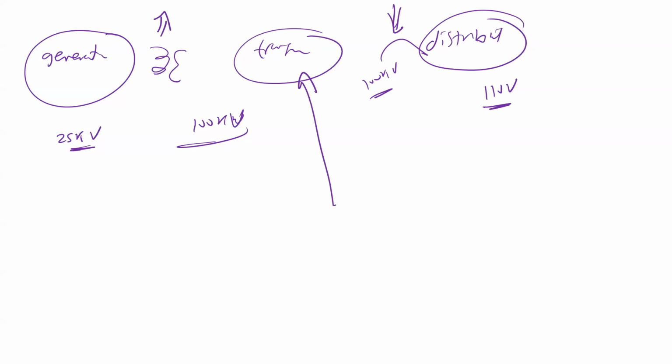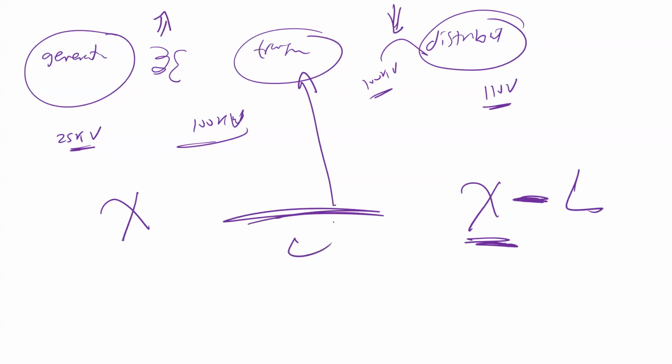But just keep in mind, if I generate an amount of power or energy X here, it doesn't mean I'm getting X here. It's going to be X minus some losses. So you lose some power. Losses are not a good thing. In order to reduce the losses, we usually need to transmit with very high voltage. So I'm just telling you why sometimes I need to use a transformer to increase or decrease the voltage.